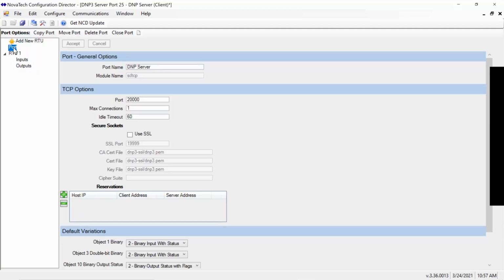It's really going to come down to application and the architecture up above, and what you want to do. As we bump up this number of max connections, let's say we had three devices polling, it's really polling just this one RTU device. So if any upstream, whether it's A, B, or C, for the site polls this RTU1, as soon as that request comes down and hits our Orion, it's going to clear out the buffer of any of the points and it's going to go out that one direction.